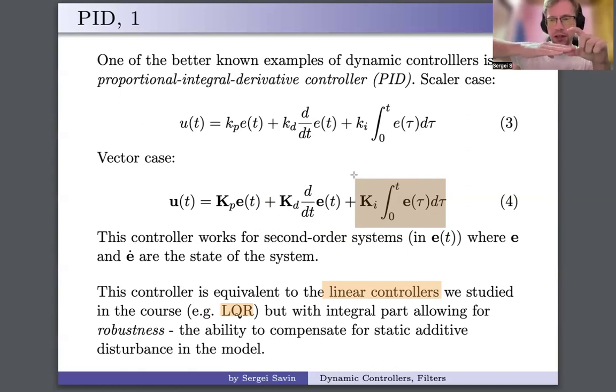It computes it, and it integrates it. Over time, this integration accumulates more and more. It is multiplied by this small coefficient ki, and over time, it's going to compensate for this lag, right? It's going to push the arm up until it hits the desired spot, at which point integration stops. I mean, integration goes on, but it is integrating 0, right? Control error is 0. So it integrates 0 here, nothing happens.